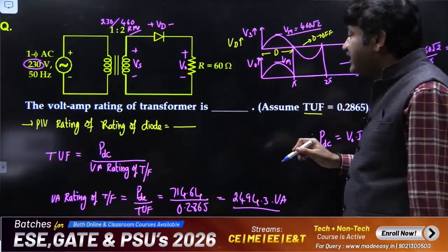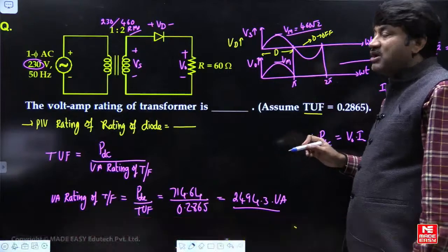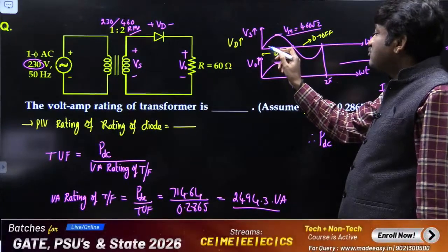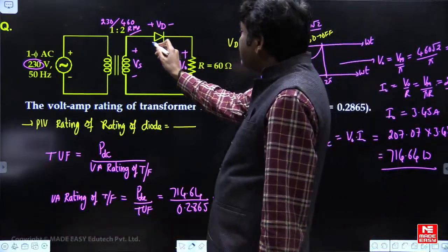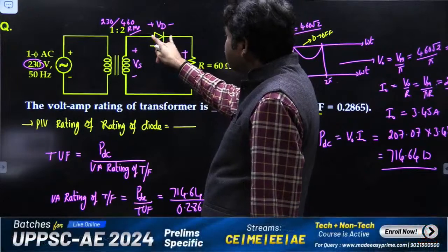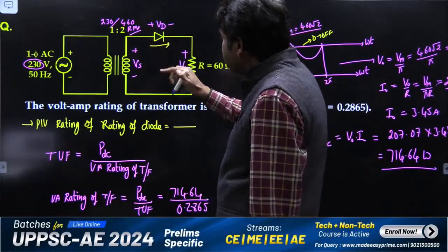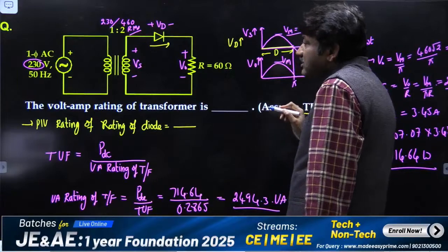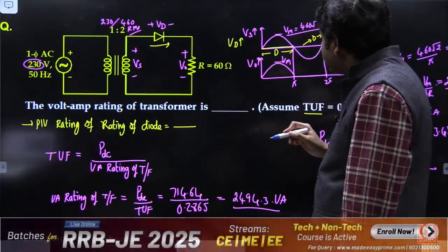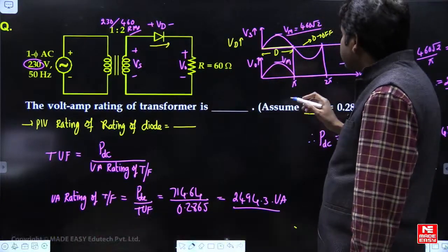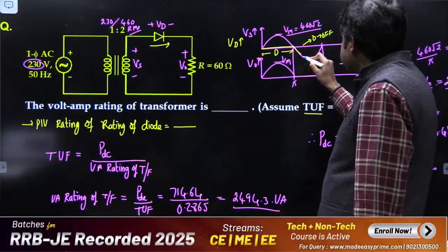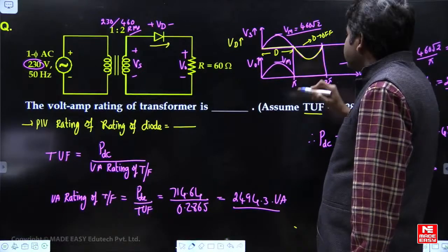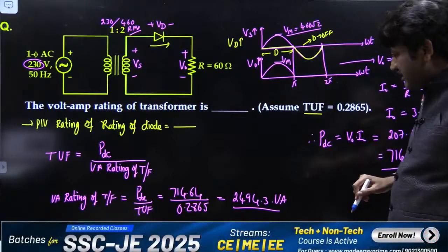Up to pi radians the diode is in the on state; assuming an ideal diode, its drop is 0 volts. In the off state, the voltage across the diode is the same as the supply voltage. So this is the waveform for the voltage across the diode.